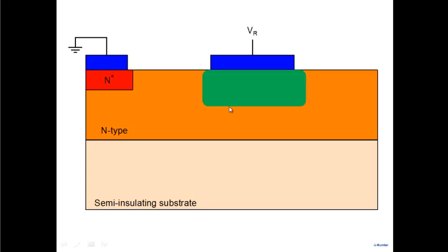This is like a semi-insulating substrate, it doesn't play a role. It's just a substrate, right? It's like an undoped, very high resistivity substrate here. By the way, if I apply a higher bias here, the depletion width increases, and the electrons are pushed out. How do they come to the metal? They are pushed out, they go here, come here, through the ground, and they come over here, right? So this provides a contact now. I don't need a contact here. I can form a contact at the top. So as you push the electrons out, as you increase the depletion width, they go here and they come here.